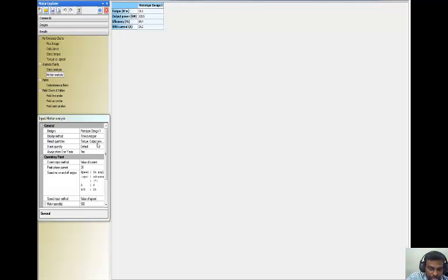The machine we designed requires around 525 watts with a speed of 500 RPM. So the torque requirement is approximately 9 to 10 Newton meter, and the approximate efficiency we have targeted is 85%. We want to check whether those results are obtained, so instead of plotting the results for different speeds, straight away I can do the time average and check the torque, output power, efficiency, and RMS current.